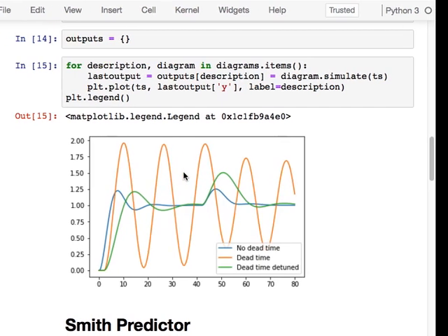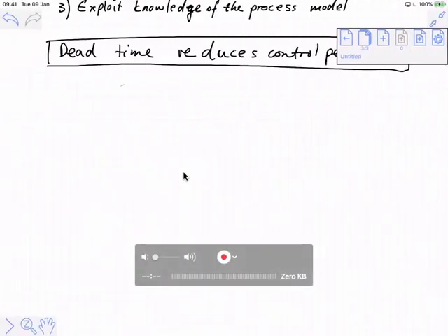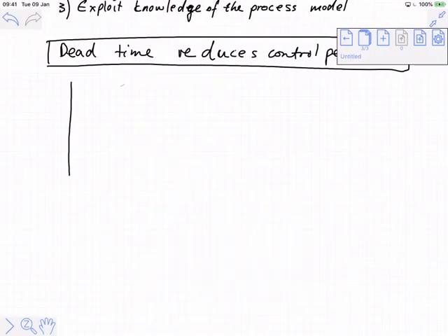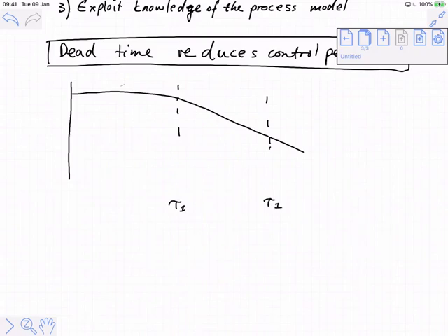But when we view this in the frequency domain, I want you to recall the frequency response of this second order system. We can sketch that Bode diagram out, and we know that for a second order system, the gain part will typically have these two inflection points, or two places where the slope changes. We'll go from a slope of 0 to a slope of -1 per decade to a slope of -2 per decade. And so that's on the gain part.